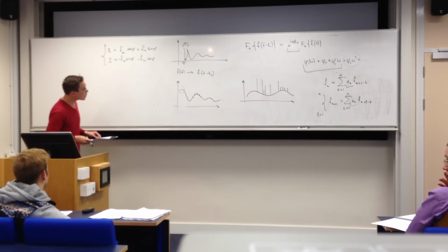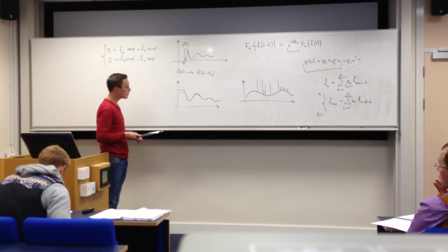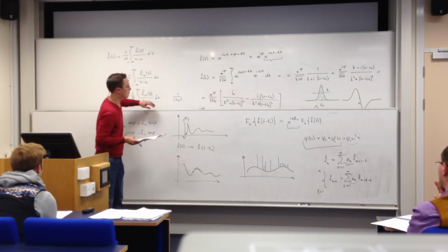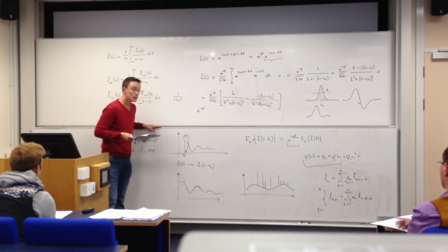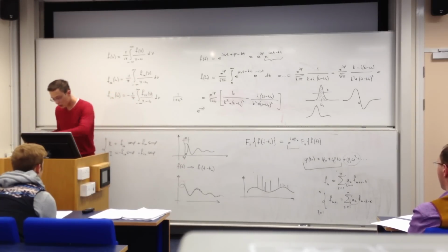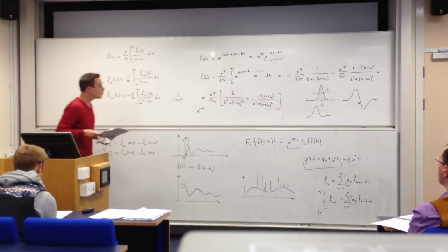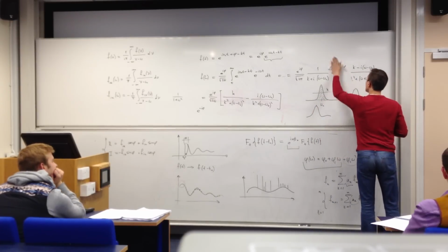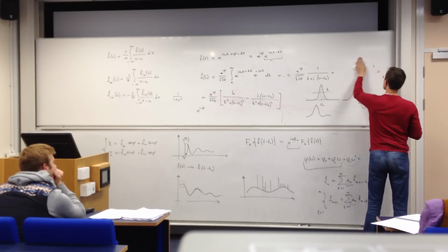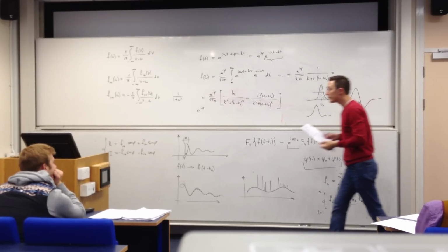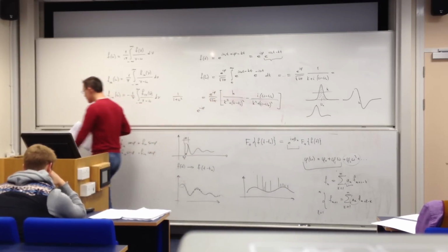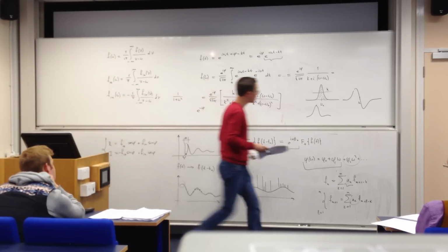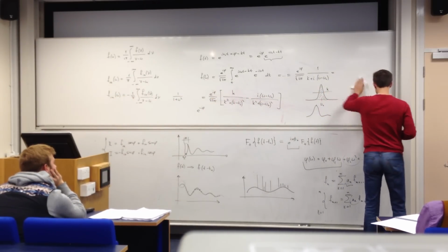Right, so this is the case of point defects. Things can get even more dramatic. That is, whole chunks might be missing from the data, either unintentionally, if something happened, or by design. If you decided to sample your data non-uniformly to save time, then the problem becomes that the Fourier transform of non-uniformly sampled data isn't actually well defined. And effectively what you have is, compared to uniformly sampled data, chunks of it are simply missing.